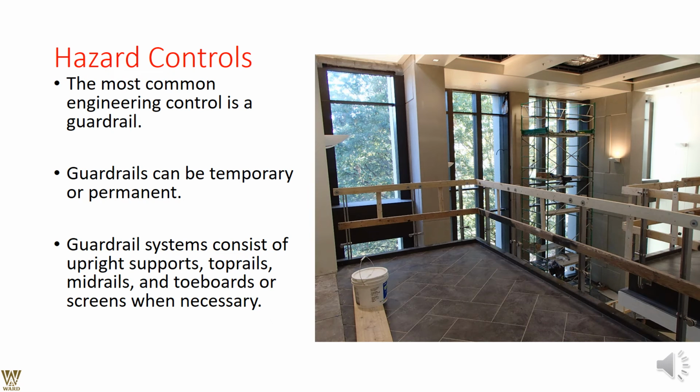We talk about the hazard control. The most common of the engineering controls is the guardrail. And if this is my guardrail which comes around it, absolutely the guardrail can be temporary, can be permanent, as long as it serves the purpose of not allowing or letting a person fall down. Well and good.